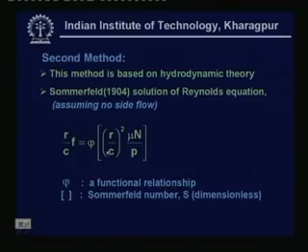if we look at the second method, this method is again based on the hydrodynamic theory of lubrication. The idea is that Sommerfeld in 1904 gave a solution of the Reynolds equation assuming no side flow.